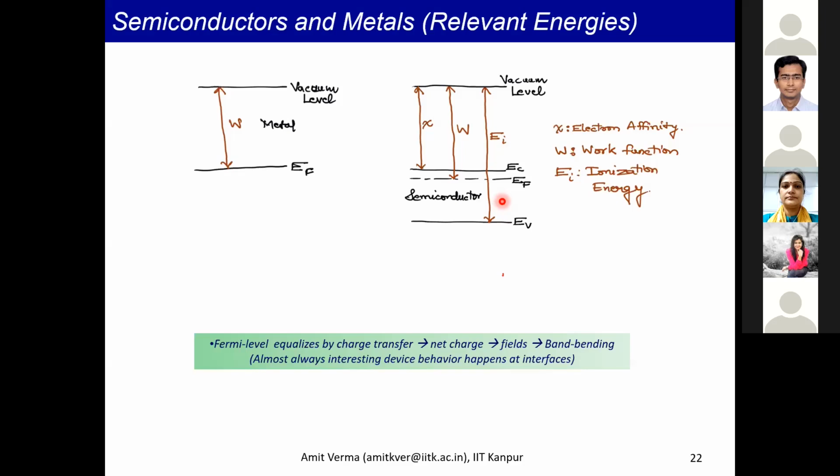Initially, suppose you have doped this semiconductor. So the number of donor ions will be equal to the number of electrons, so the material will be neutral. Now, when you bring two materials together and, say, this one loses electrons to the other material, this material will no longer be neutral. Now there will be a net positive charge in this material. And that net positive charge is what leads to band bending, or shaping the potential energy landscape.